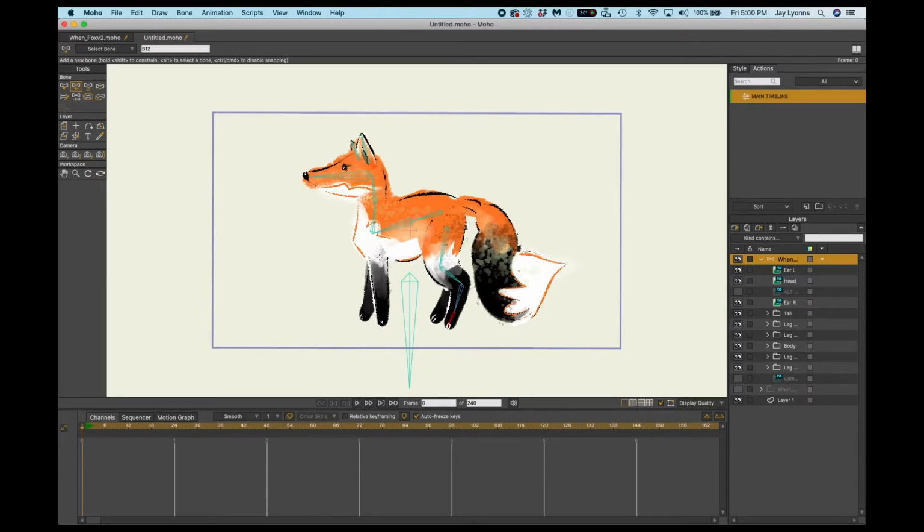So now we're going to start creating the bones for our front legs. We're creating the legs for the left side of my creature. We're looking at it from the left side. With my Add Bone tool selected, I can hold down the Option key and select the chest, and then begin dragging to create a bone for my front leg. I'm going to use 3 bones in this front leg. Start by clicking on the rotational axis of the top of the leg, and drag down to create 2 more bones.